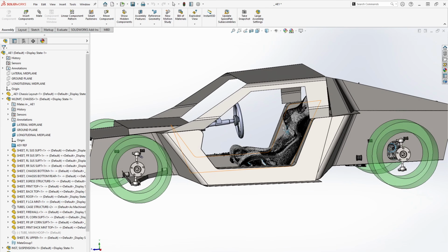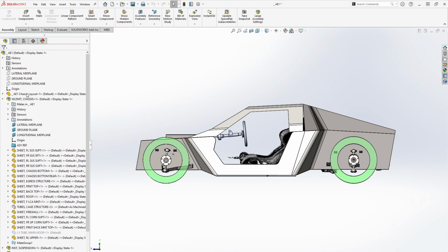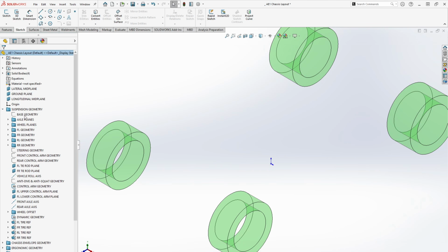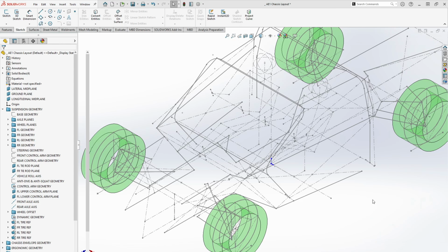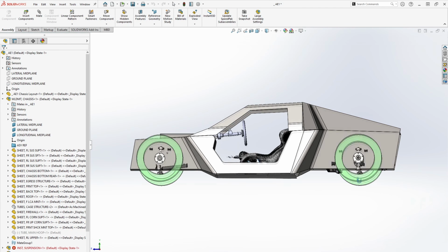And as one more example, I'll go to a side profile of the car. So right now I've got a wheelbase of 104 inches. If I open up this, now I could edit that part file in the main assembly, but I just choose to bounce back and forth a little bit and give SOLIDWORKS a second to update. Again, I've got this wheelbase of 104 inches. Let's say I jump this up to 110. Give it a second to update, because it's updating just about everything. And you can see I've got a vehicle that's an extra 6 inches longer.